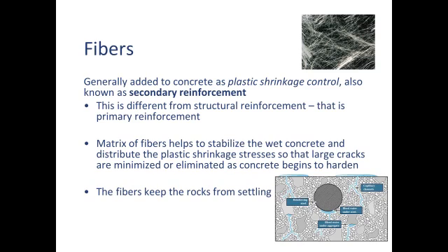Because here's what we're trying to combat. If you just had an ordinary concrete mix that came out of the truck, but it had too much water in it, comes down the chute, you spread it out, bull float it, waiting for everything to happen. As it's sitting there, gravity is pulling down on everything. So gravity is causing the rocks and the sand to settle. Big rocks settle faster than small rocks.